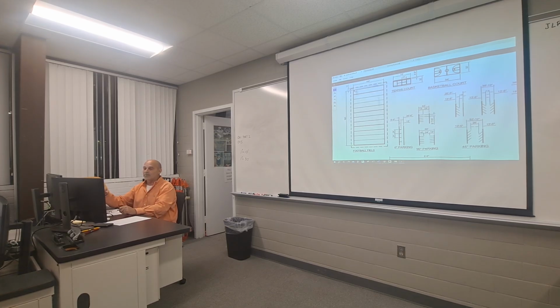We do that a lot, so you have some layers that are no print layers. You have your VP or viewport layer, you have your reference layer, that are on that sheet that I put for you in Blackboard with the layers, so put those on there. Feel free to make any other ones that you need. Stuff like easement lines, we're gonna have easements that we're gonna be dealing with on this project that we don't want to print. But we need to be able to see them while we're working, because if they say you can't go in this area because there's an easement there, and you design a project and you've got a football field, you've got a track, building right there on that easement, you just killed the project and really made yourself look bad.